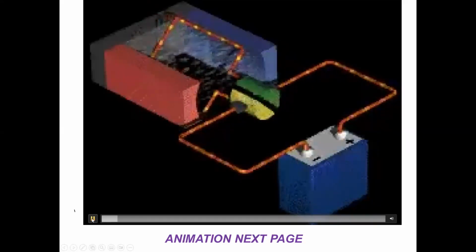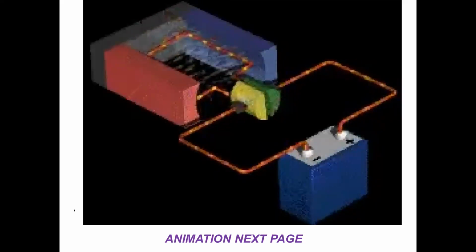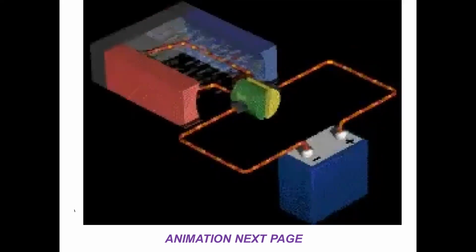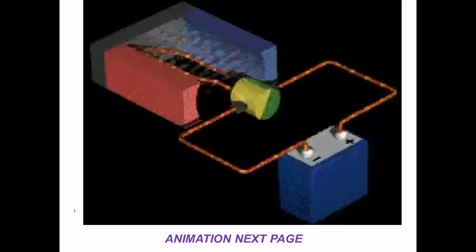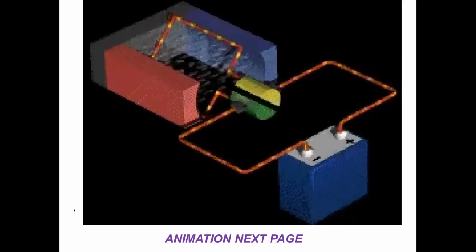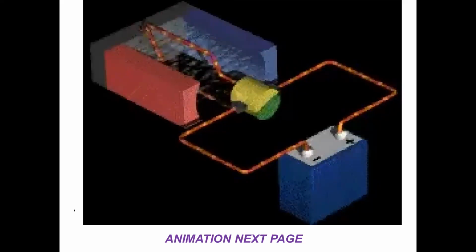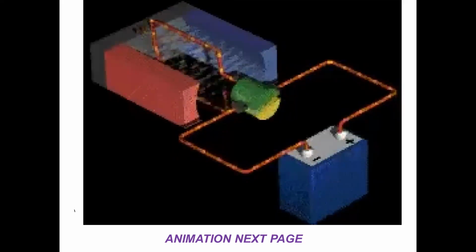In this simple electric motor, a current passes through a coil in a magnetic field. This forces the left side of the coil upwards and the coil rotates. When the coil is vertical, the current shuts off for a second. The current is reapplied and the other side of the coil moves upwards. This is the simplest model of how electricity creates mechanical energy.